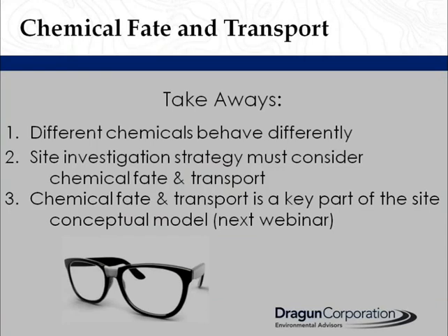So a few takeaways from this, hopefully. I know we went through it fairly quickly. Different chemicals behave differently in the ground. For the site investigation strategy, you must consider the chemical fate and transport, meaning your design of your wells, how deep your screens are, where you put them aerially.